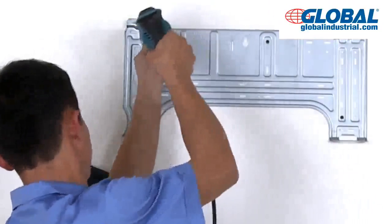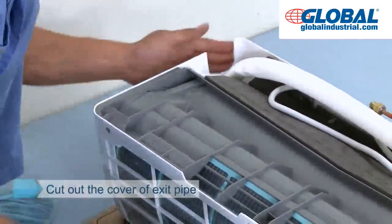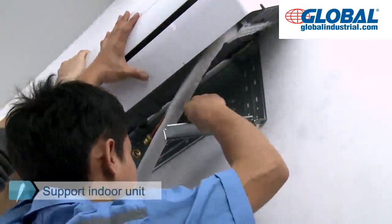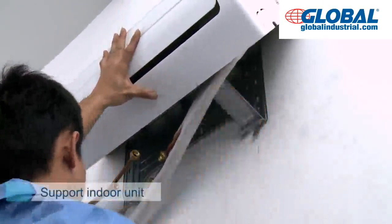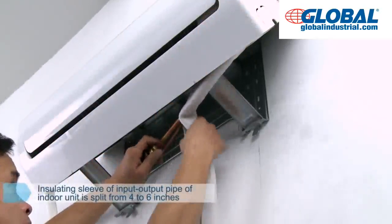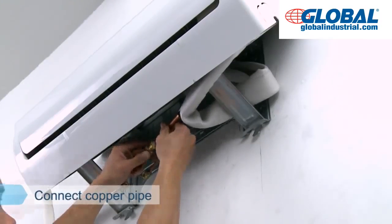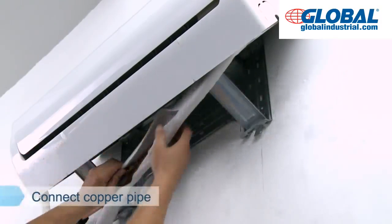Fix the mounting plate. According to reserved position of wall hole, confirm the direction of exit pipe and cutout cover of exit pipe. Remove drain pipe. Installation auxiliary bracket is threaded through hole of mounting plate to support indoor unit. Insulating sleeve of input-output pipe of indoor unit is split 4 to 6 inches to facilitate the connection. Connect copper pipe. Note that copper pipe should be free of bending and deformation.